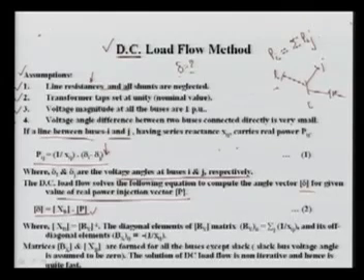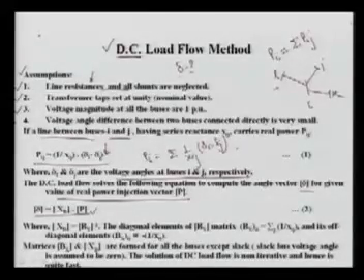So from this expression I can write this Pi at an individual bus. It is the summation of all the power flow, that is 1 upon xij times delta i minus delta j. Here we sum over all the connected lines, meaning the buses j, k that are connected to bus i but are not i, and we keep on adding.